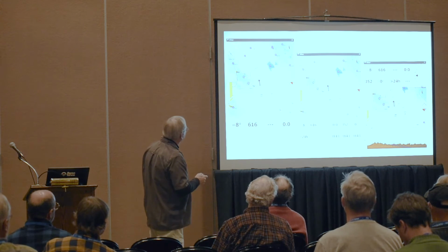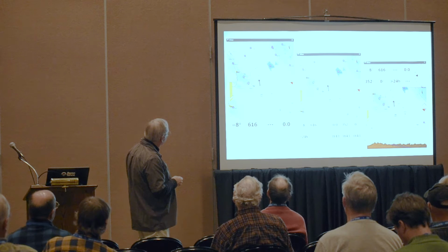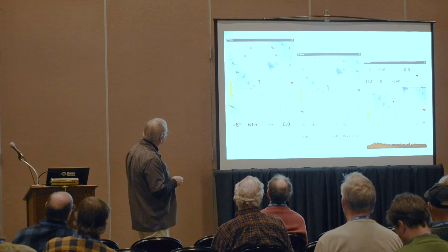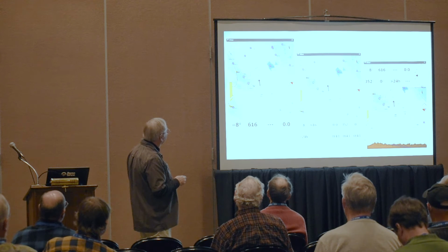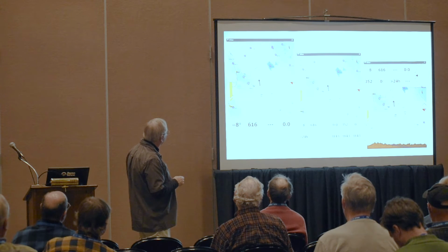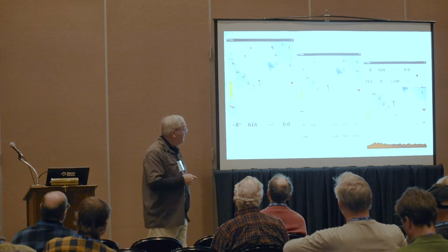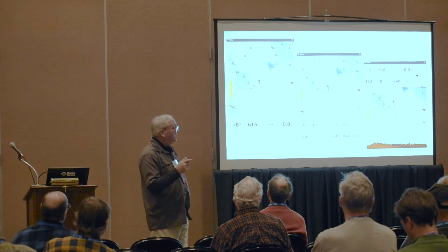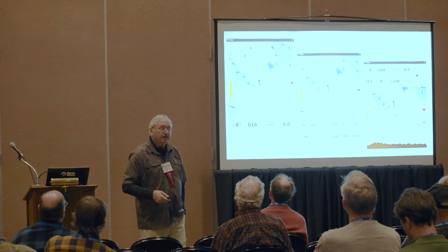If you look really carefully here, you can see a brown line that's kind of jagging around. This side of the line, which is where the glider is, is a little clearer than this side. This is called shading. You can change a lot of things, but it's hard to get the shading to be really clear unless you do a couple of other things. Nevertheless, this line basically tells you how far you can reach with your glider at the current McCready and at the glide ratio of the glider that you've got selected in the setup.